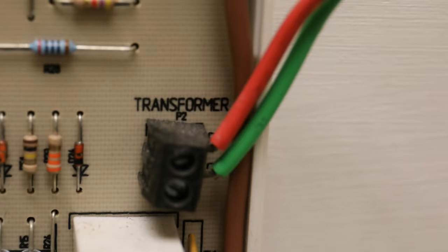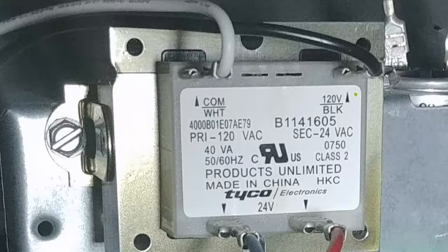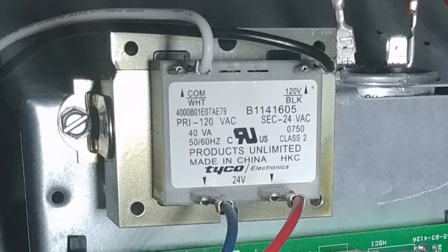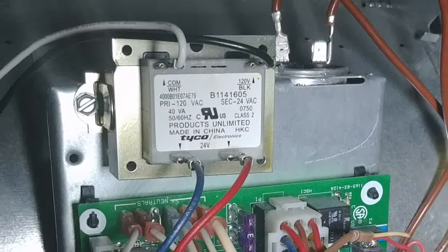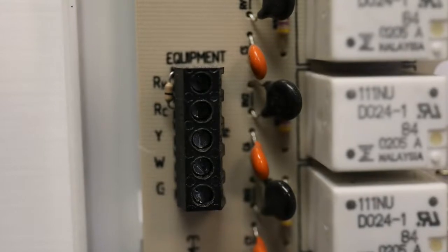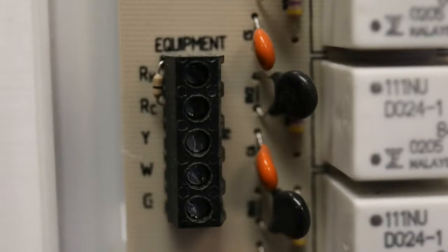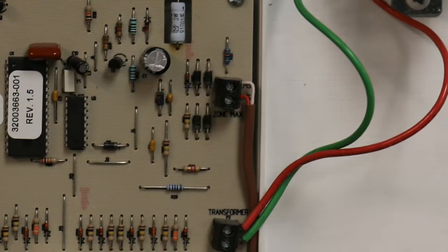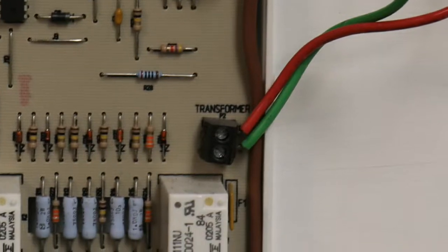Inside the zone control panel is a dedicated power terminal from an externally installed transformer. The transformer inside the furnace is usually insufficient to power both the air handler and the zone control panel, thereby requiring the installation of a dedicated transformer just for the zone control panel. This means that there will be two separate 24-volt power supplies going to the zone control panel, one from the air handler equipment and one from the dedicated zone control panel transformer. Care must be taken to keep these two sources of power separate from each other, since they may be out of phase with each other.